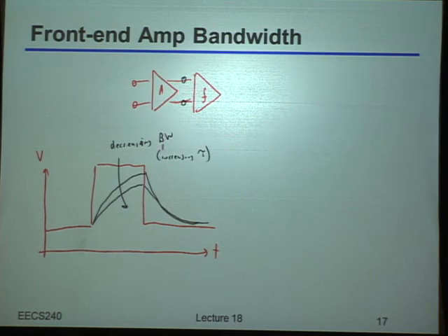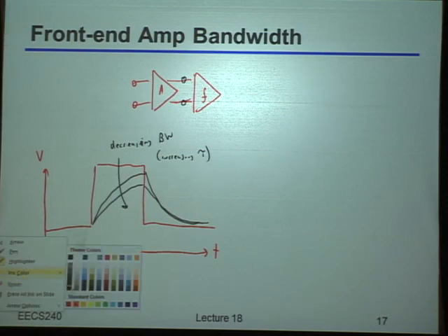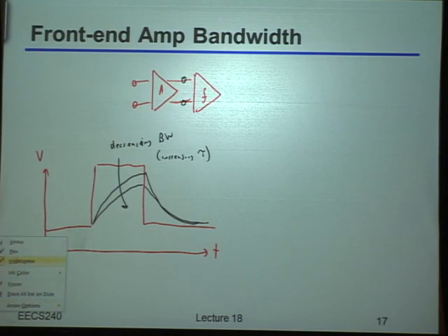So what we're really doing here is, I could make that bandwidth infinitely big, at least in principle. But it would cost me a huge amount of power to do it. And the point really is that, if I did it, and let's just draw that example, let's say that I really did spend a ton of power, so that I had really, really great settling accuracy, well, would that really buy me any extra signal? No, not really. Right? Because I've already settled perfectly to whatever the input signal actually was. So that means it probably never really makes sense to make the bandwidth so large that you completely settle out and you have no residual settling error whatsoever left.